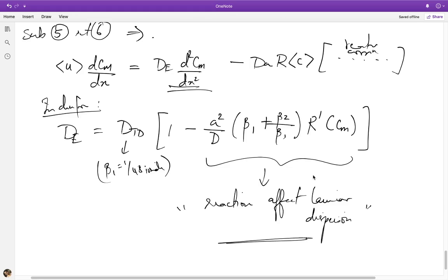Why? Because typically when we model non-ideal reactors, what we do is we do the RTD study, right? So in a presumably non-ideal plug flow reactor or a laminar tubular reactor, we carry out a residence time distribution study where you put in, let's say, a plug of solute and you observe the outlet concentration, and from that you try and calculate. If you fit the result to Taylor's dispersion model, you can empirically get a Taylor dispersion coefficient. And then we use that dispersion coefficient inside an axial dispersion model of the form I've written on the screen, something that looks like this.